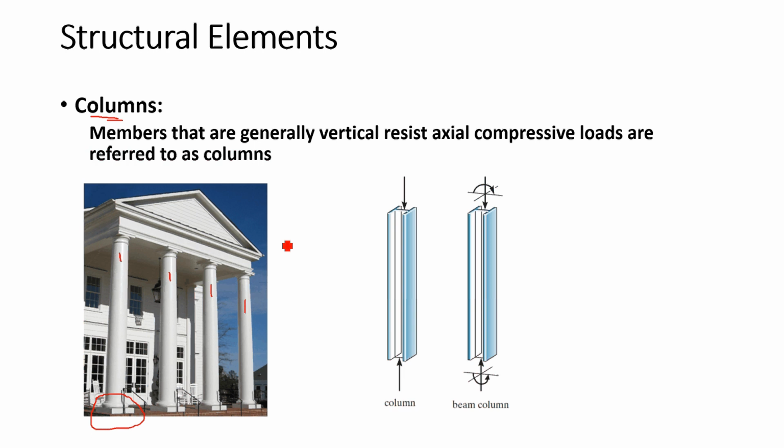Whatever load you apply in these buildings, there may be loads on the floors. Loads come from the users, sometimes furniture, sometimes a big sofa. Whatever load you apply to the structure, finally all the loads reach the earth, going to the soil, your ground. The path by which it reaches the ground is the column.